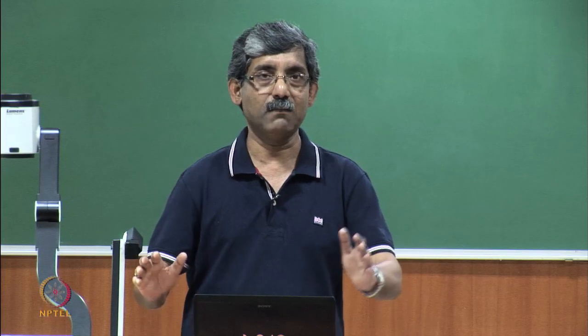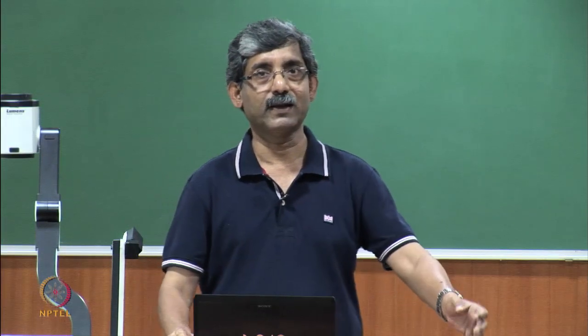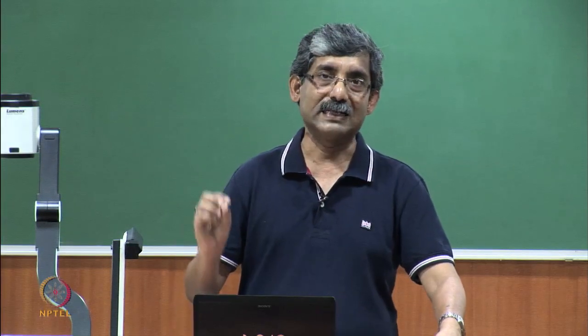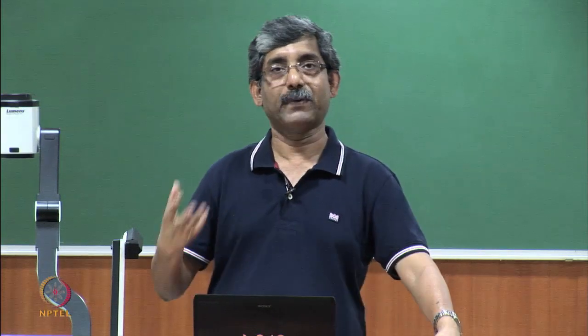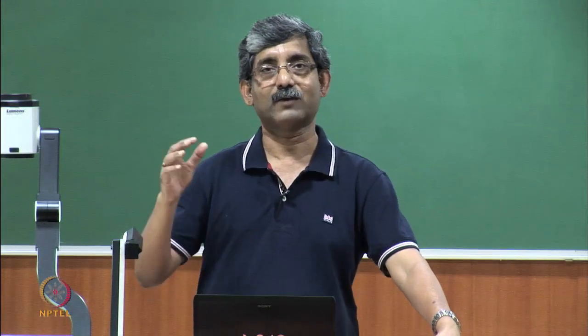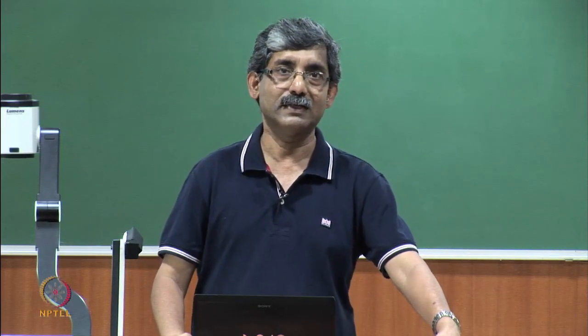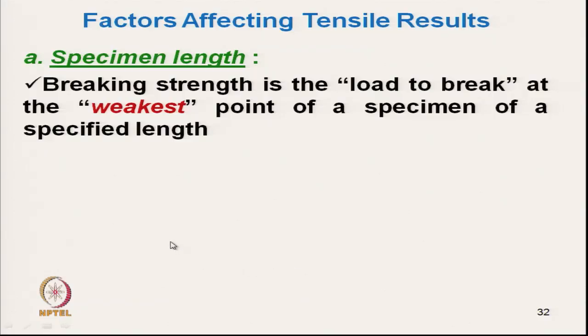Specimen length directly affects the tensile result. For the same yarn, if we increase the specimen length, the apparent tensile strength becomes lower, that we have seen. So, the basic thing is the weak link theory that we have discussed earlier. The yarn, any material as a matter of fact, breaks at its weakest point.